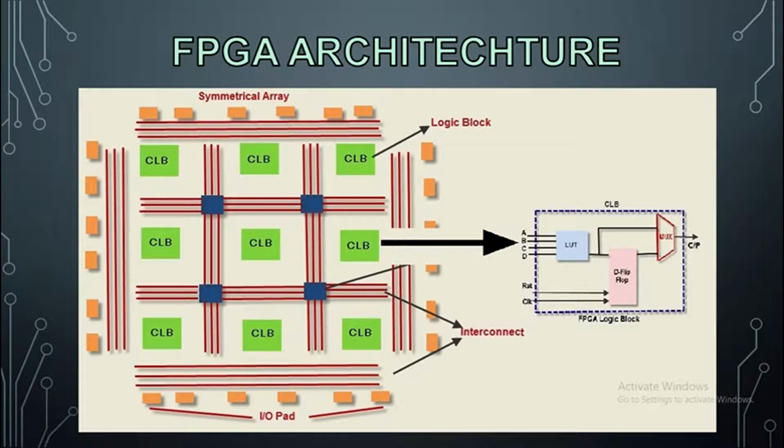A CPLD is simply several PLAs connected together to form a macro cell, also called a LAB, which stands for logic array block.